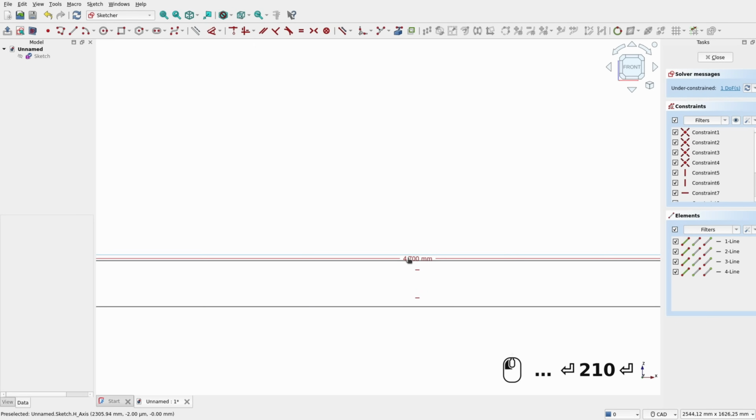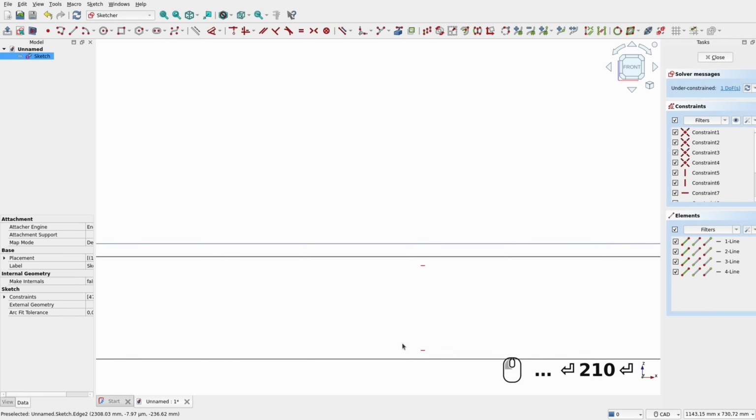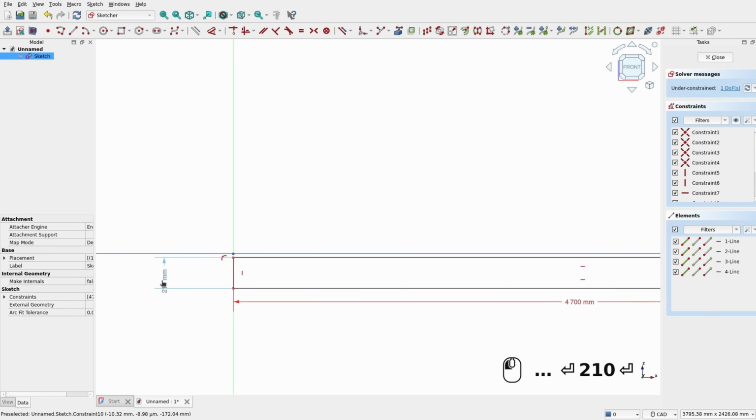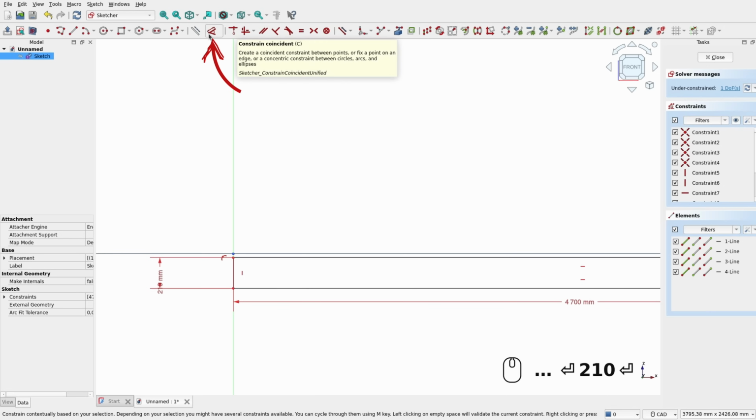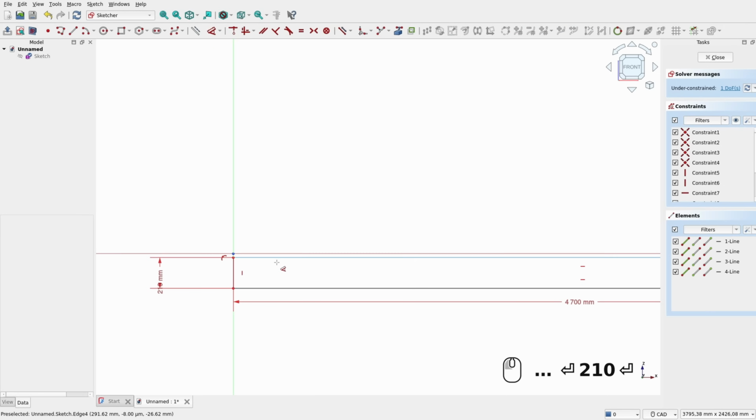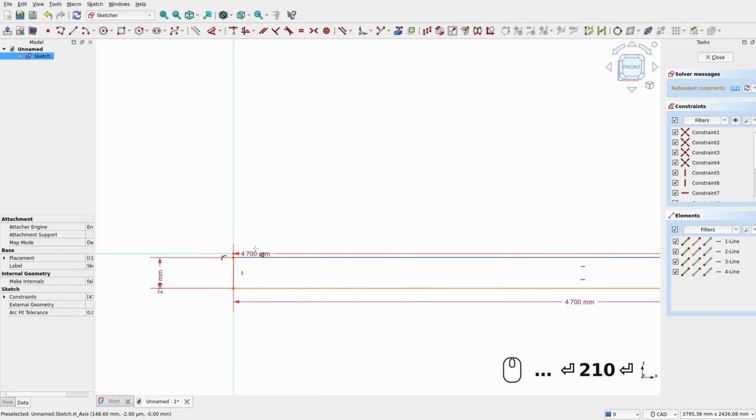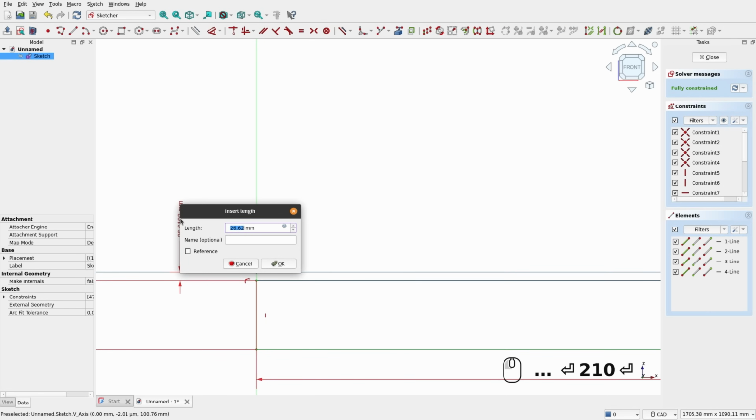You can drag the red dimensions around by holding down the click to make things look a bit cleaner and more spaced out. Now let's set a dimension for the gap between the red axis and the slab. Head up to the top menu and pick the Dimensions tool. Then click on the top edge of the slab, followed by the red axis, and set the dimension to 100.